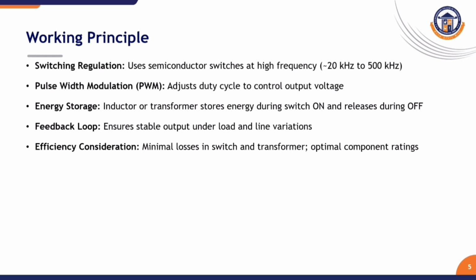Next, we are going to discuss the working principle of SMPS. The SMPS works on the principle of switching regulation. The switch operates at higher frequency, typically 20 kHz to 500 kHz. The output voltage is controlled using a pulse width modulation technique. By adjusting the on time of the switch, the output voltage is regulated.